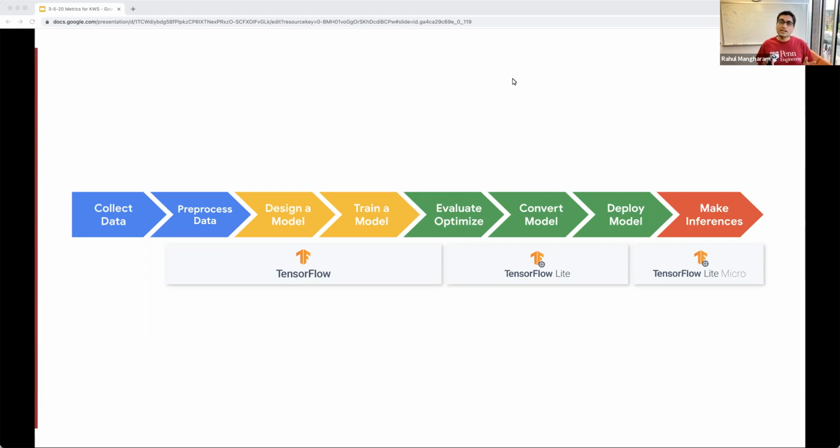You've gone from understanding how to collect the data we're using, that's the Speech Commands data set, and pre-processing that data to spectrograms and applying mel filter banks. Then we made the model small by inherently picking a neural network architecture that is confined enough that it would fit on our microcontroller device. And then you've gone through the exercise of actually training the model. And now we are at the stage where we want to understand how to assess the keyword spotting model.